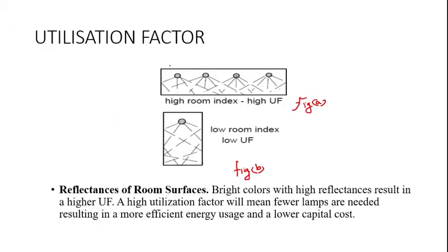The width of the room is very high compared to the length, and the mounting height is comparatively low compared to figure B. So case A has a higher value of room index, and a higher room index means a high utilization factor.